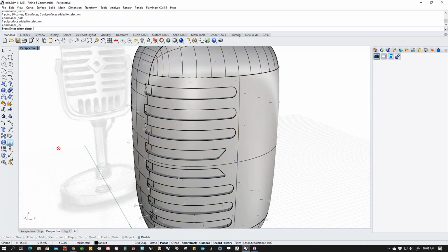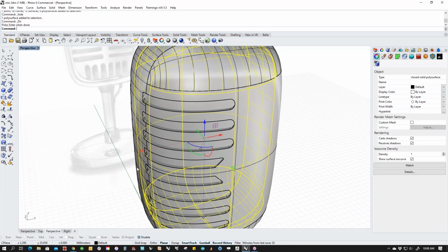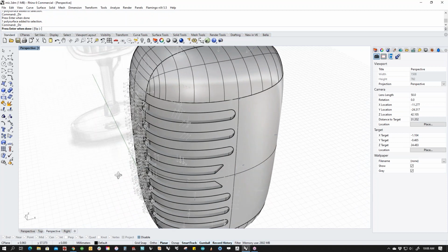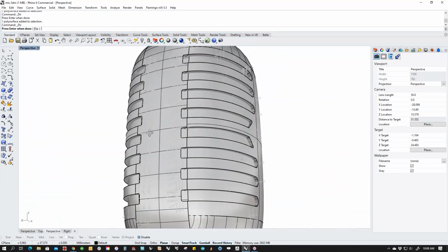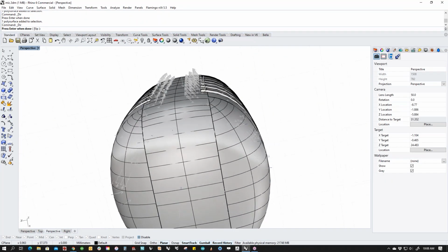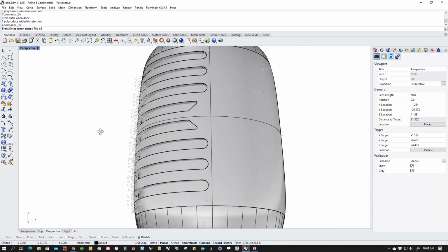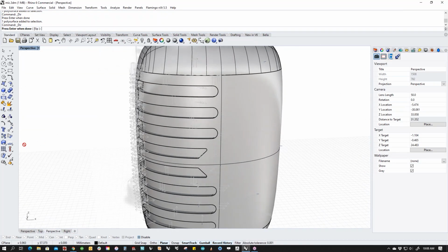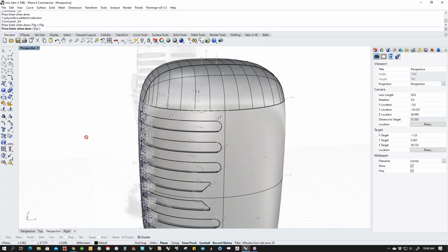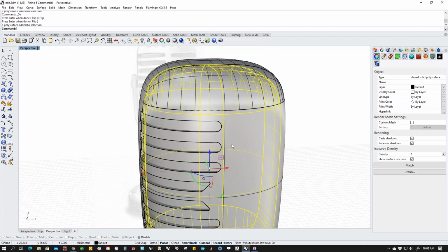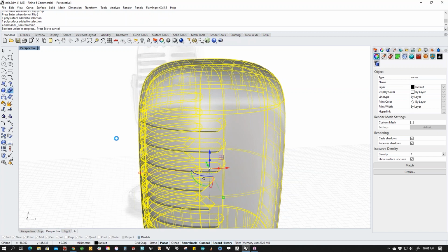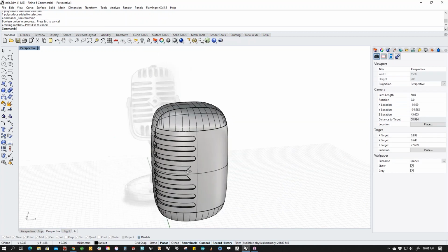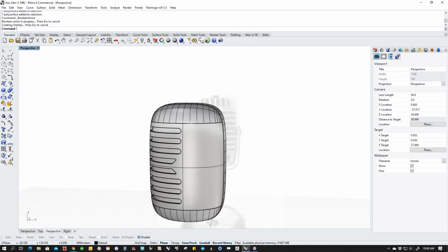The direction on that is pointing out. The direction on that is pointing in, it looks like. So let's flip that one. And now let's do the Boolean again. If your Booleans are backwards, it's a direction issue. There we go. That did what I wanted it to do.